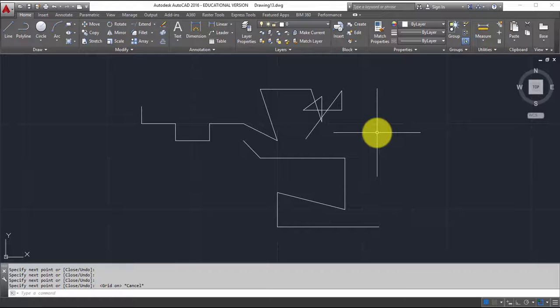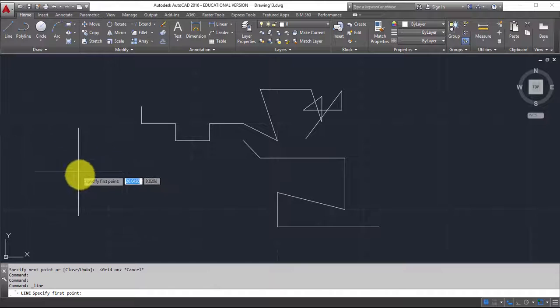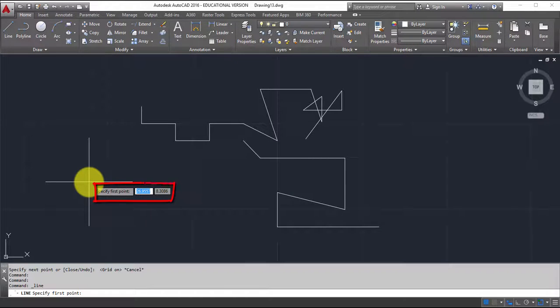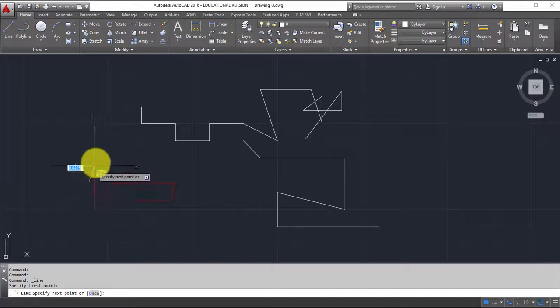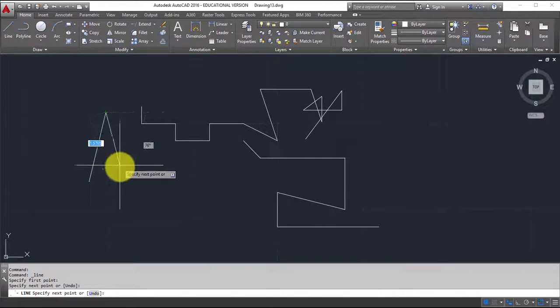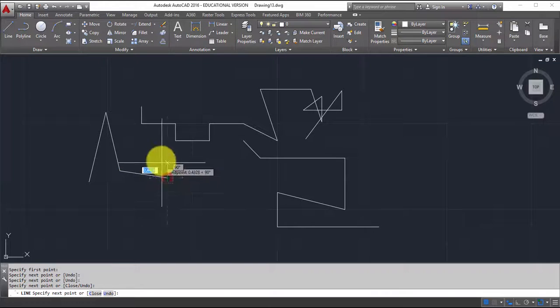The next control that I want to show you is the dynamics control. Now this is a pretty sophisticated tool. So I've turned it on. It goes back to AutoCAD's desire to create what they call a heads-up display. Let's see what happens when I start drawing a line. You'll notice immediately that there is a series of information there right next to my cursor. And as I draw, that set of information flies around the screen with my cursor.